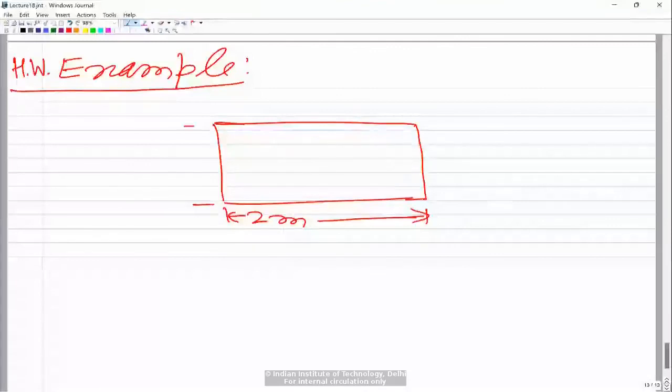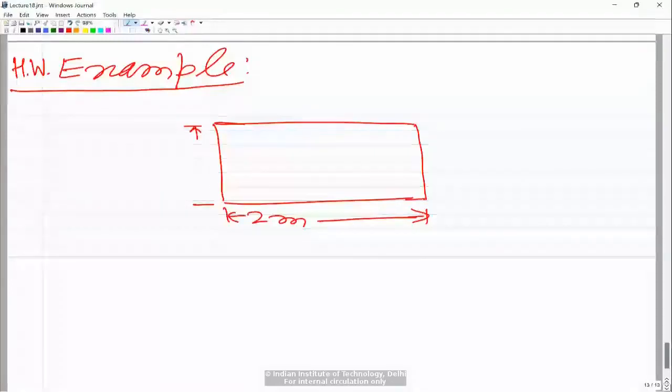Recently we were doing one design of a piping system for the pump in a ship. We were doing that design in the department. So we had a piping where there were many supports. Because we wanted to model the problem as a whole, we had to use 3D finite elements. But ideally, the pipings could have been modeled as beam elements, and the supports could have been modeled as plane stress and plane strain elements.